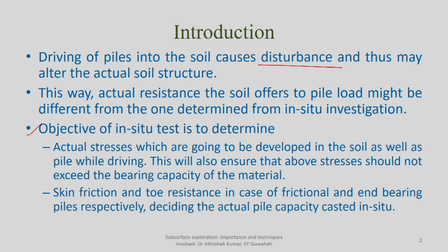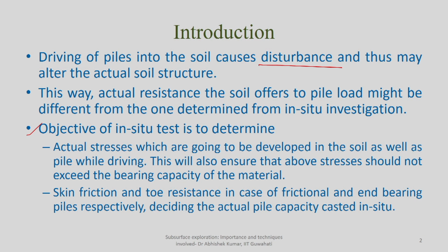One is the actual stresses developed during impact load, because we know that pile driving means you have a pile head over which you provide hammer impact, as a result of which the pile is gently pushed into the ground. The actual stresses developing in the pile cross section should be significantly lower, so that they will not cause any kind of shear failure either in the material of the pile or in the surrounding soil.